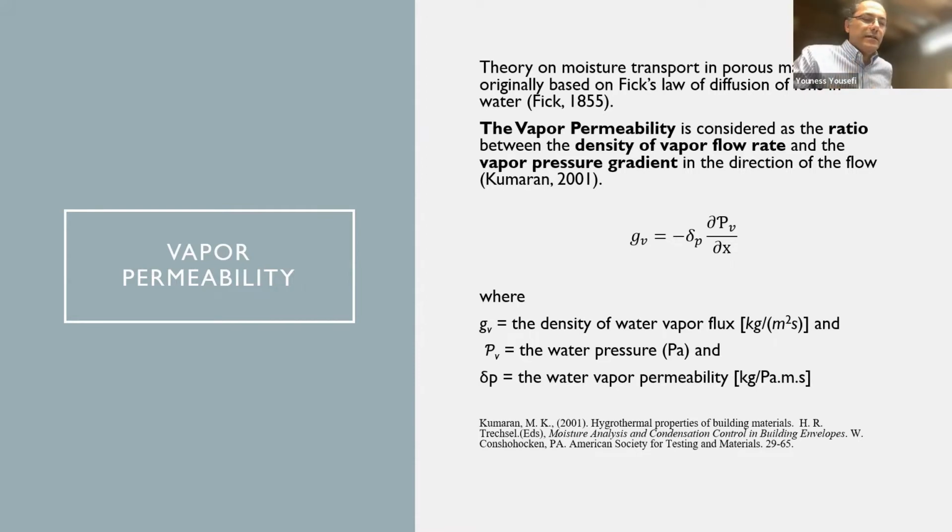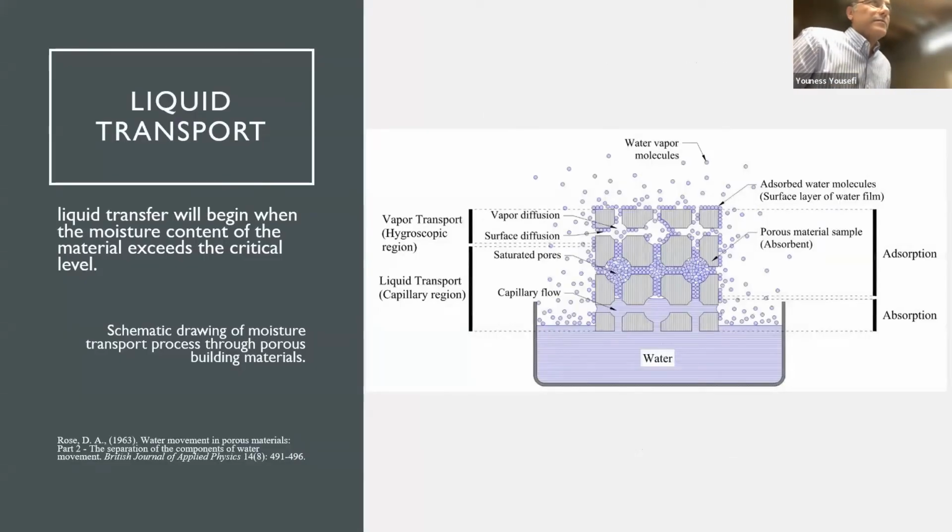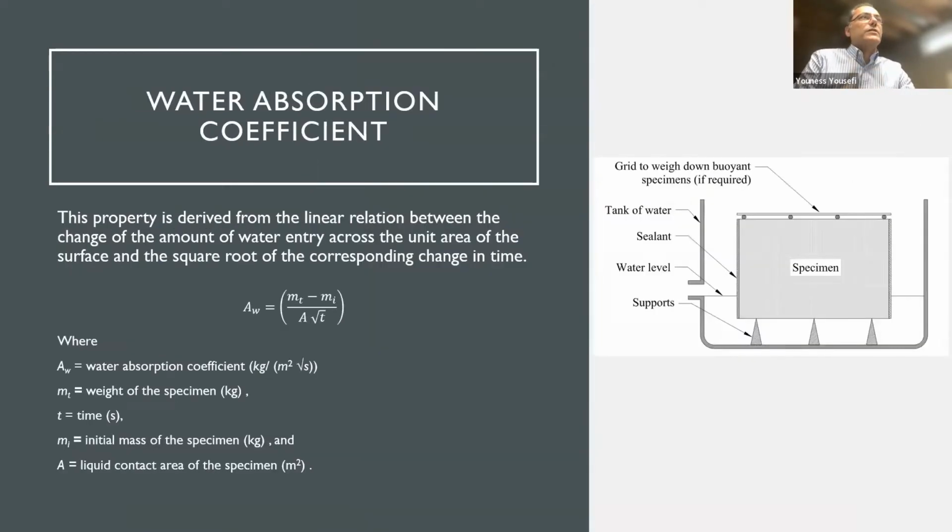So it was a very sophisticated procedure among the others. After that, for measuring the liquid transport through the material, we used the partial immersion, immersing the material into water. So the material was in contact with the surface of the water and started the capillary flow, absorbing water from below, and of course it goes again through different phases until it reaches the top of the building material.